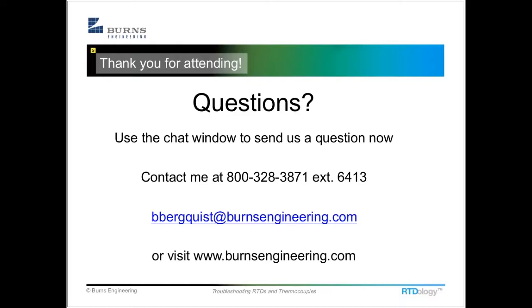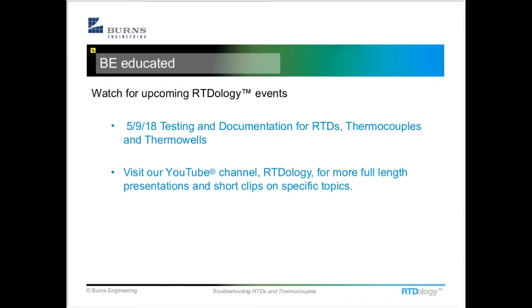Jeff, yep, I took a quick look. It doesn't look like right now we've got any other recommendations on or recommended manufacturers for heat transfer paste or even type of transfer paste? You know, one of the real common ones is similar to the heat sink compound that's used on integrated circuit type stuff. It's just, I think it's zinc oxide and a silicone oil paste. It's got a good temperature rating. It's good to about 200 degrees C.